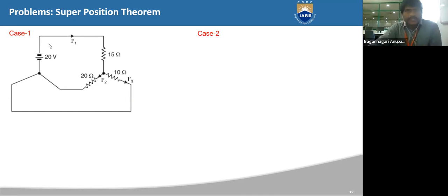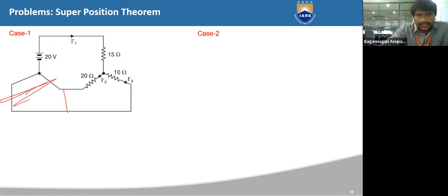See, if you consider this circuit, since we are shorting the sources here, we have replaced the sources with a short circuit here, right? So it doesn't make any difference even if I join these two like this, or if I consider these to be a short circuit, right? That means these two terminals are one and the same up to here, right? Both these lines are one and the same. So you can simply draw the circuit with these two elements, right?